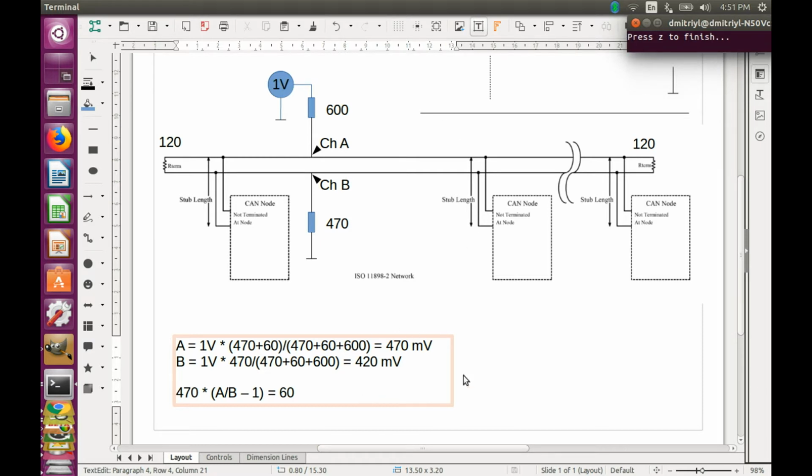If we notice that these voltages jump around or change values when we wiggle some connectors, it will mean that there is a wiring fault in the system. And we can catch it by using masks and alarms in the PicoScope software. This test will allow us to easily notice faults like a short from CAN low or CAN high to ground, a short between the CAN lines, or loss of terminating resistors.